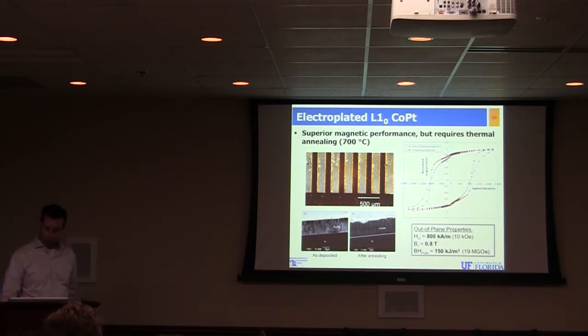If I understood you correctly, you talk about thin films, yes? It's vertically magnetized. And the charges will create a very strong demagnetizing field, which degrades the performance of the magnet. Can you comment on this? Right. So that's why the difference you see for the in-plane curve in red, the demag effect that you're talking about here is the difference in this black curve. That's the discrepancy between the raw measured in-plane and out-of-plane properties.